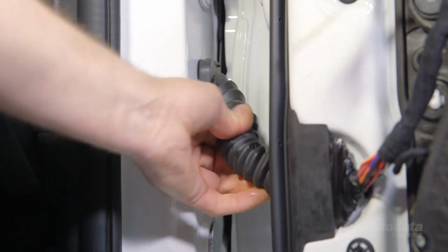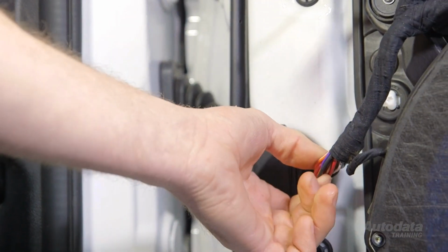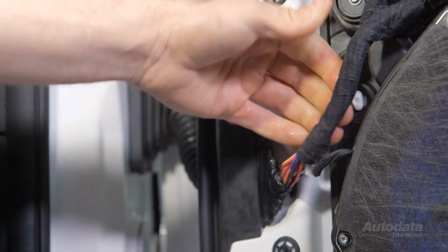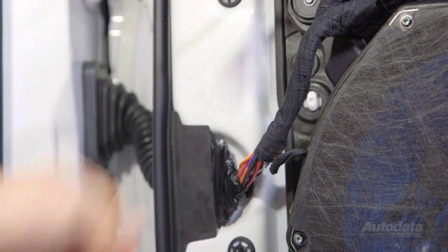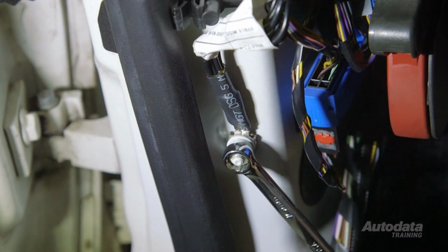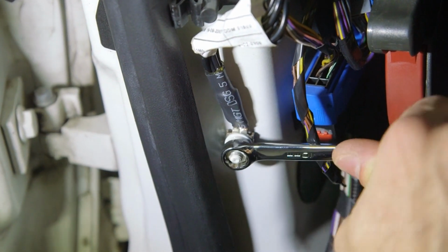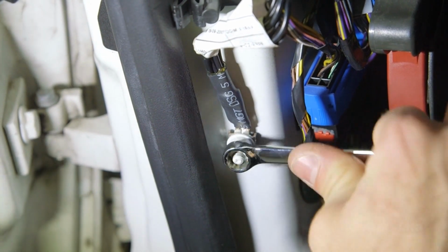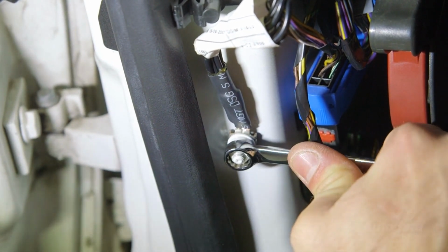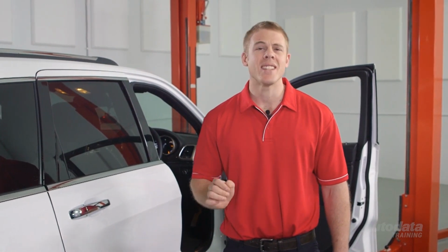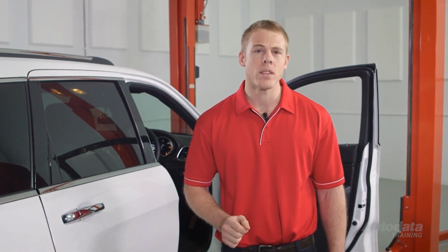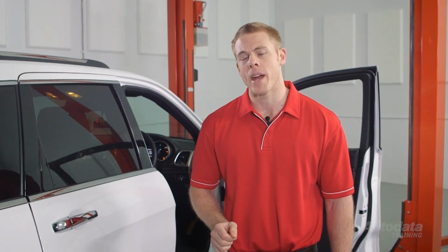Inspect the wiring on the inside of the door. Make sure it's free and not contacting any moving parts. Confirm it hasn't been pinched or crushed by the window regulator. If the vehicle has been in an accident, ensure all earth points relating to the LIN circuit haven't been painted and are secure. The key to any successful LIN diagnosis is to understand how that system works and what checks we need to perform on that circuit.